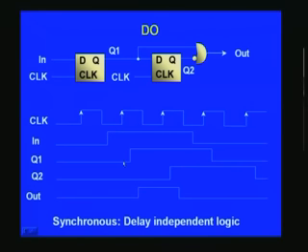That should have happened here, but owing to the delay between the clock and the Q output, it is staggered a bit, delayed a bit, and otherwise this is nothing other than the input itself. This in turn is applied to another flip flop, and that output is also a delayed version of this particular Q1, and once again we get it here in this fashion.